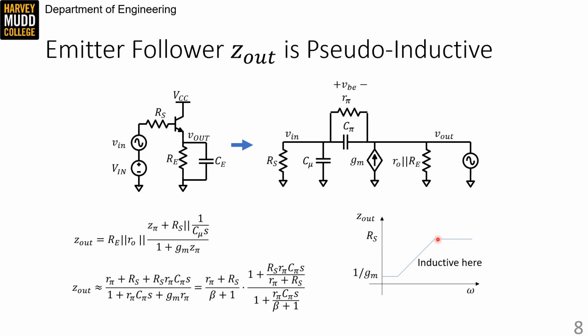Now, over a broad range of this, though, our impedance is increasing with frequency, just like an inductor's would. Their impedance is j omega L. So our output impedance looks inductive over that frequency range, which can result in undesirable ringing, again, especially if you have large capacitive loads.